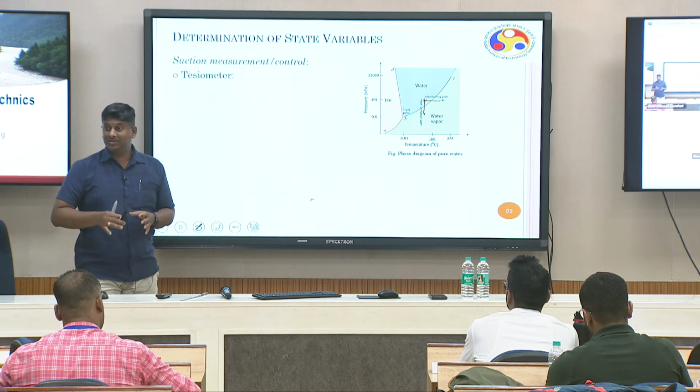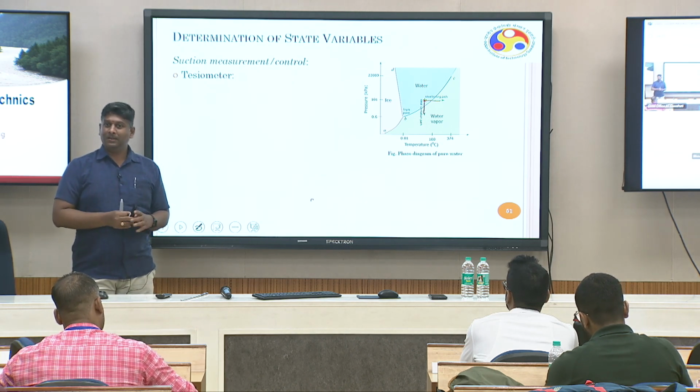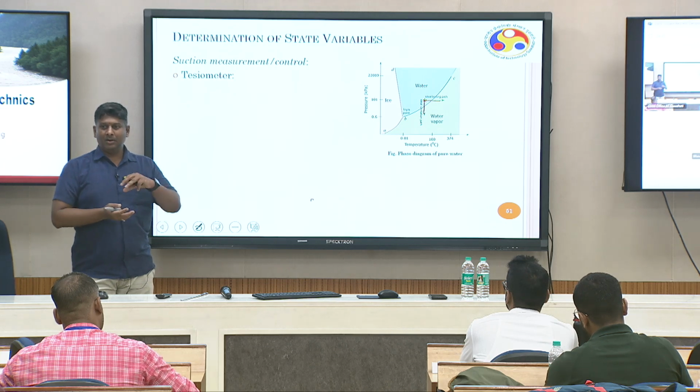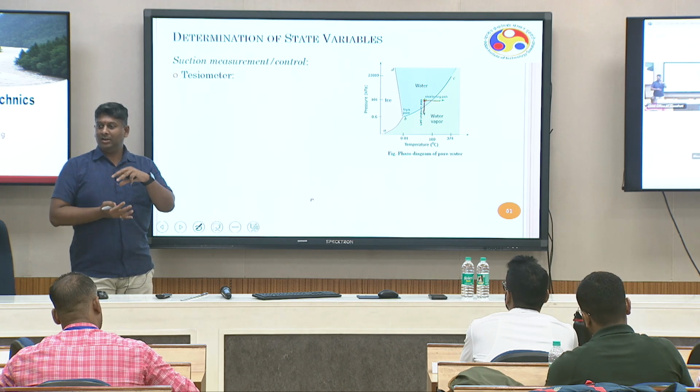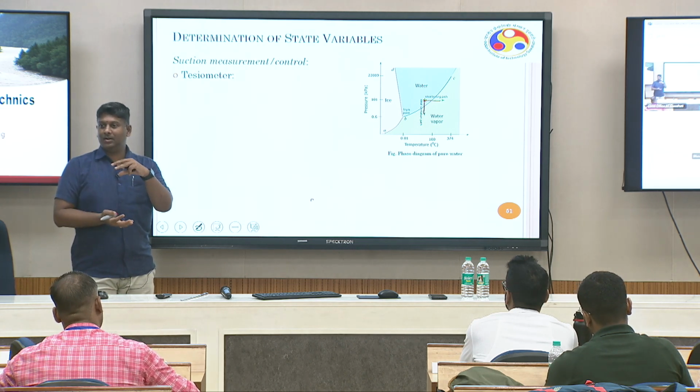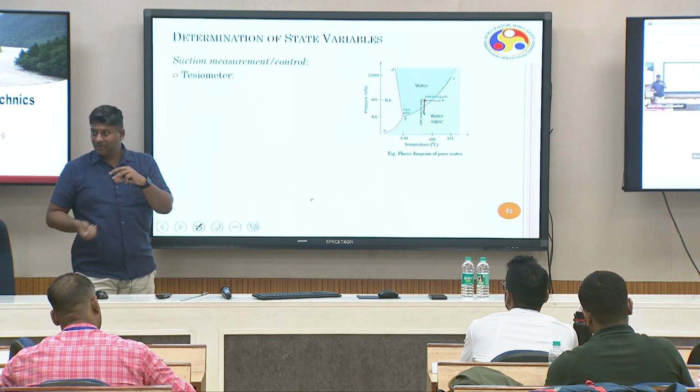If the back pressure is low, then this can happen. Because if you remember, it has a tendency to expand if it is a drained test. In an undrained test, it can't expand, but the pressure drops. It goes to negative, right?